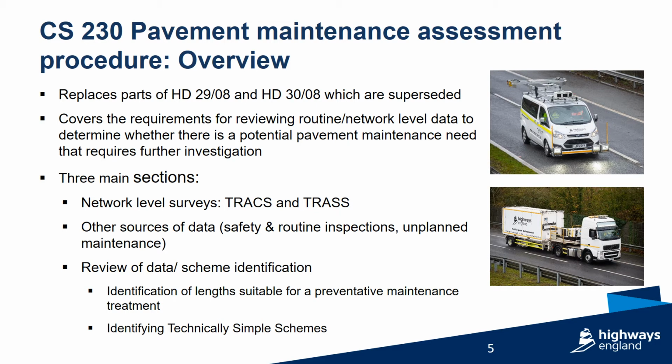CS230 Pavement Maintenance Assessment Procedure replaces part of HD29 Data for Pavement Maintenance and part of HD30 Maintenance Assessment Procedure, and these old standards are superseded. The new standard is divided into three sections: the network surveys, other data sources, and the review of data for scheme identification.